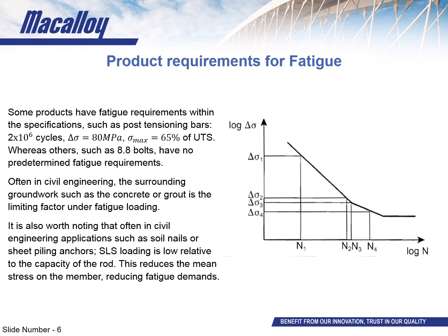So SLS loading, if people aren't aware, is just the loads that the bars themselves experience on a regular day-to-day basis. What this can mean for the bars is that for a similar stress range, the mean or average stress, along with the peak stress, is lower, and this reduces the fatigue demands on the system.